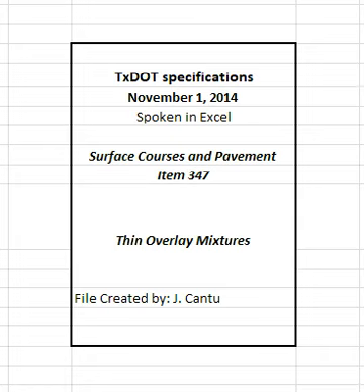For exempt production, the contractor is relieved of all production and placement sampling and testing requirements. All other specification requirements apply, and the engineer will perform acceptance tests for production and placement listed in Table 10. For exempt production, produce, haul, place, and compact the mixture as directed by the engineer, and control mixture production to yield a laboratory molded density that is within plus or minus 1.0% of the target density as tested by the engineer.